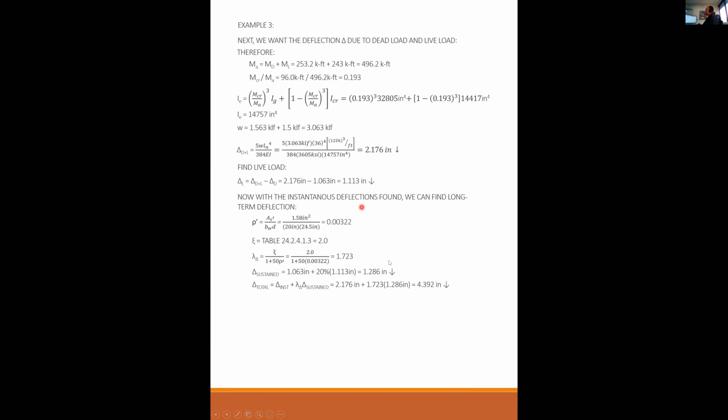So this is very important, something to be aware of as concrete designers is this whole concept of creep. Because it takes something that might have been kind of close to begin with, and then it makes it totally unacceptable. Like that's way too much after 5 years. Okay, so there's a very important topic to understand.